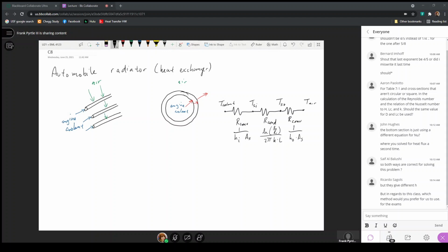So in chapter 8, we're looking at, well, if a fluid is moving through a pipe, how do I find the heat transfer coefficient that exists along the length of that pipe so that I can come up with an average value? Now, when we're considering flow through a pipe, or what we call internal flows, again, we still have to consider the hydrodynamic problem and its effect on the thermal problem.